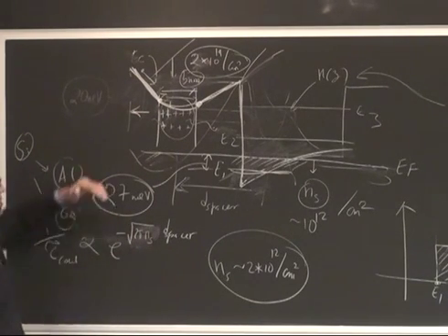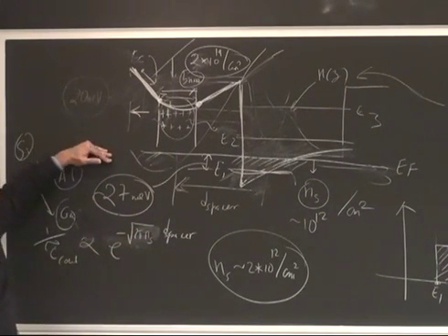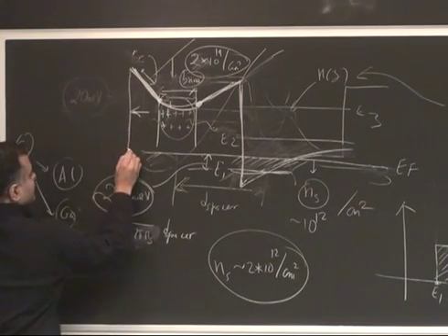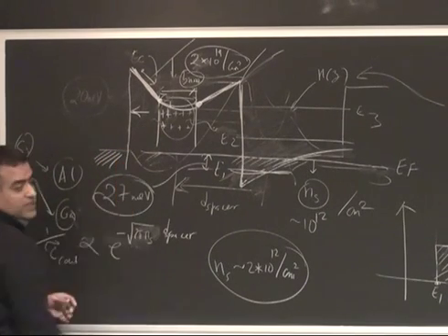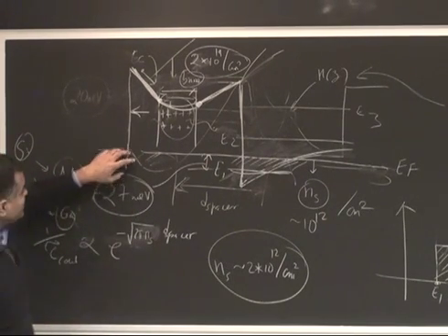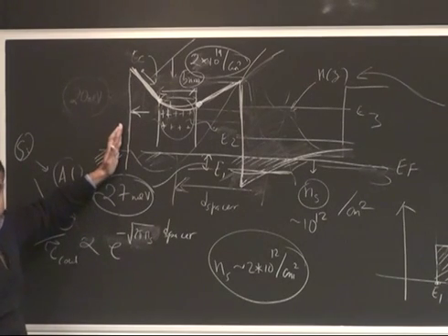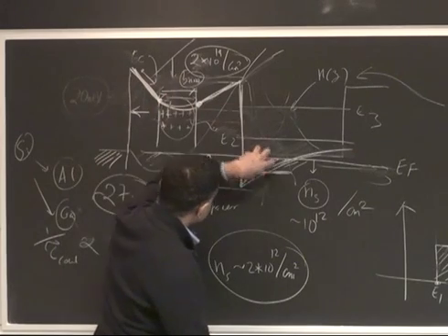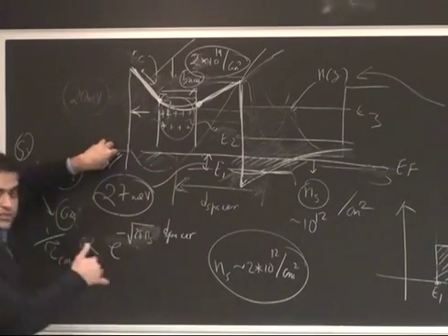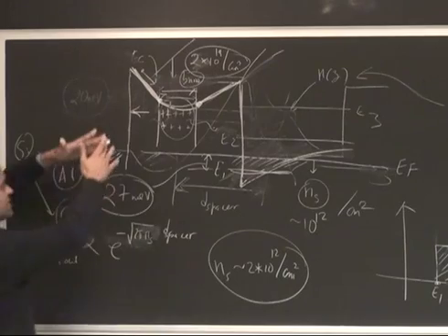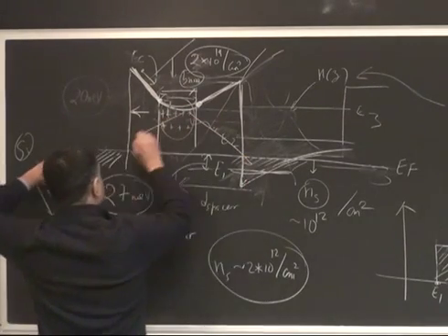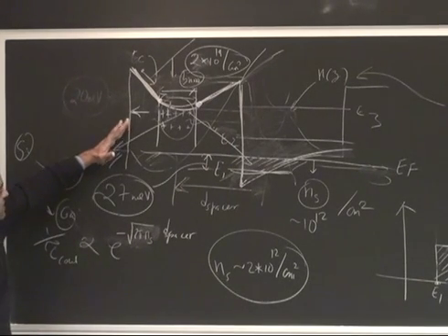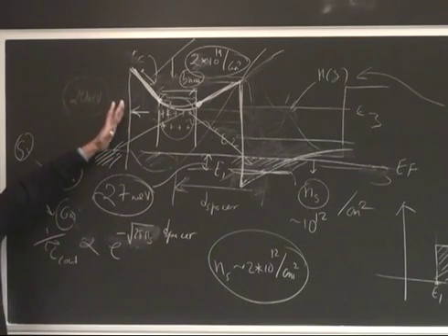So it's a misleading figure because we're not showing what's on the surface. The surface is typically a metal. It's a HEMT, so you have a gate metal here. The metal has become charged now. Of the electrons, 1e13 total, 2e12 went here and 8e12 went to the metal. So there's a lever rule: some electrons go here, some go there. That's the resolution really. That's where the electrons are.